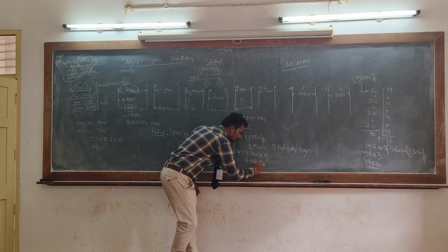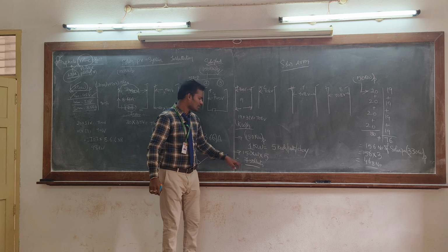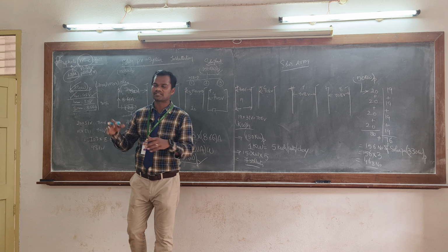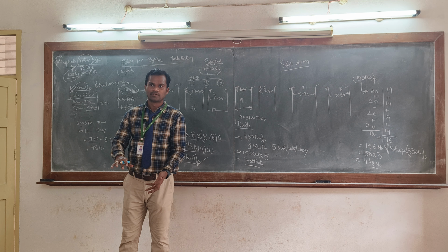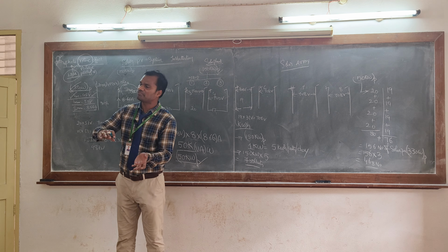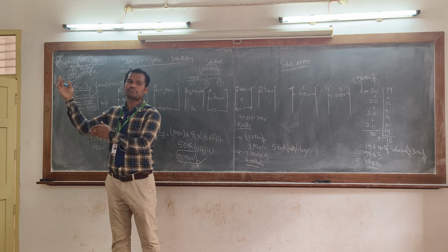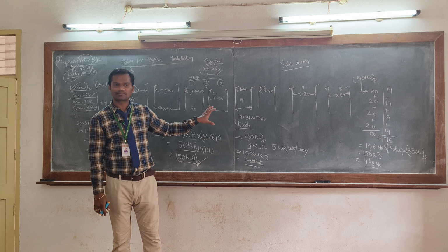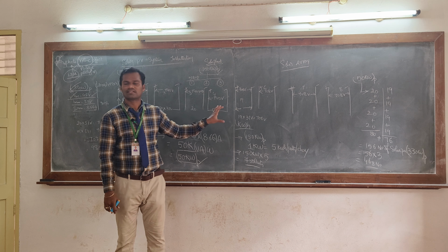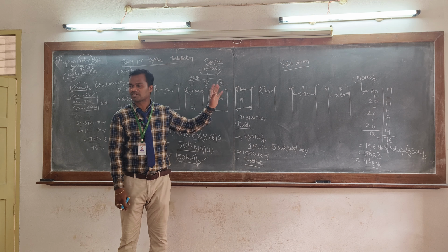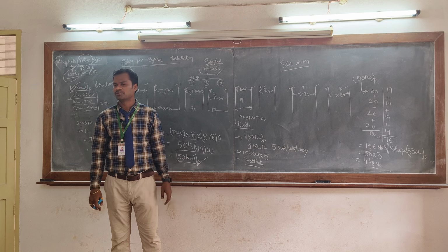750 units. So from our electrical block, we are generating 750 units. For example, of the 750 units, 400 units we will consume. In 750, 400 goes, how many are left? 350. 350 will be exported to the government, and the government will pay money to us. This is called a net metering system, already explained in the class. Does all this come under an on-grid system or off-grid system? On-grid system. This is an on-grid solar PV system. Do you have any doubts?